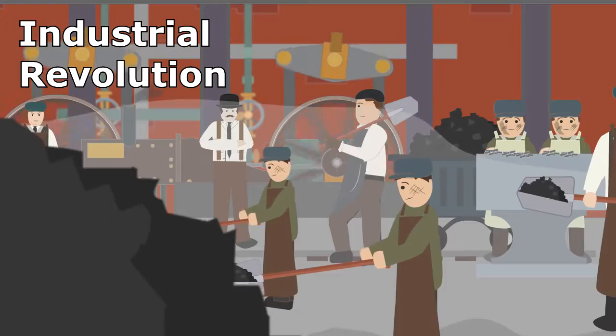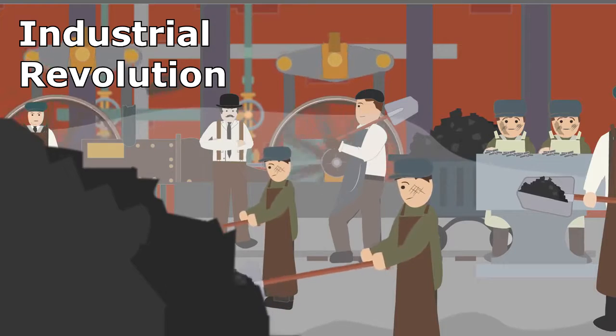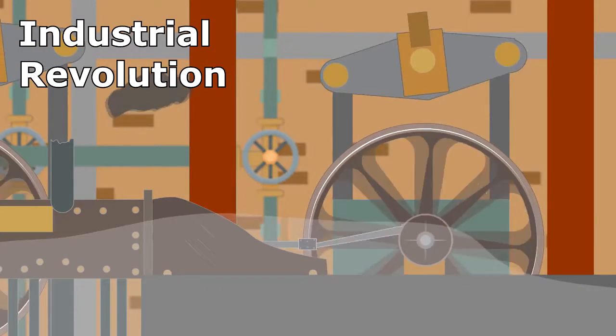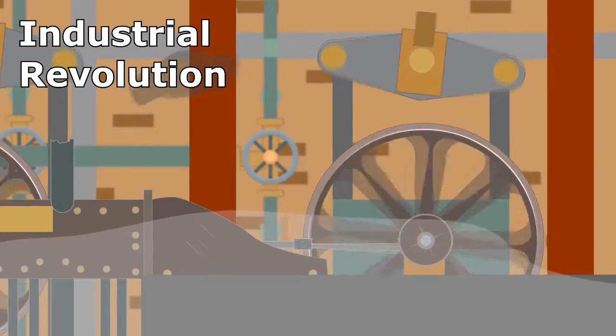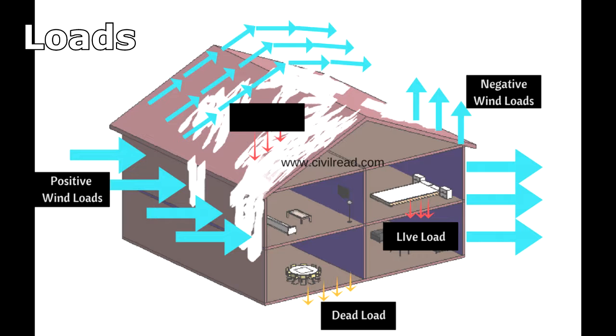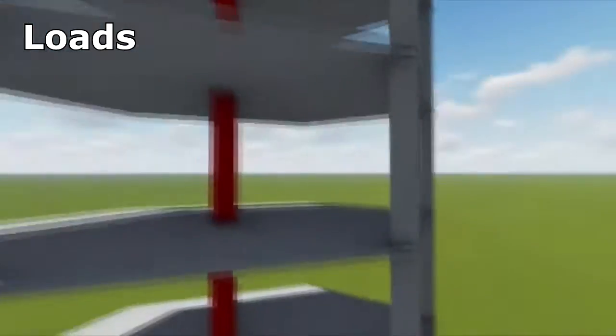Over time, the construction methods of industrial buildings have advanced, allowing for a wide variation of possible designs. Portal framing and sawtooth framing would have to be the most popular. To select the members that will be used in construction of an industrial building, the loads must first be evaluated to determine the required strength of each member, including, though not limited to, dead load, live load, and wind load.